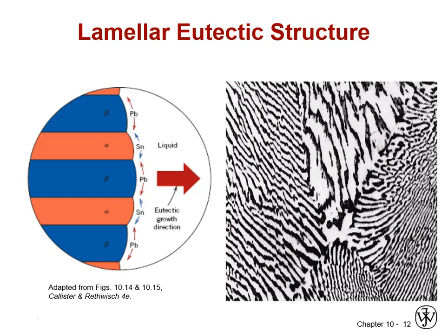Okay, diffusion is really important, and lucky for us, it happens really fast in a liquid. The fast diffusion that you can get in a liquid can allow us to wildly segregate to nearly 100% ahead of a solidification front and form these fabulous layered structures that occur spontaneously on solidification or on crossing a phase boundary, even in solid solution.